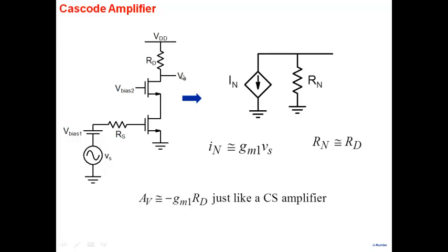Wherever you want to calculate something gain, all that you do is, suppose you are interested in gain at this point. I will just do a calculation again. At this point, then what you do is you build Norton's equivalent at that point. At that particular node, build a Norton's equivalent, which means that the whole circuit, looking at it from this node, would be like IN RN.